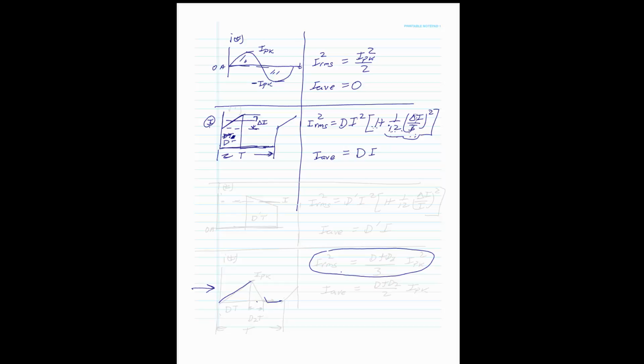The next one you'll see, of course, on the boost and the buck boost, is the diode current. And what are you going to see? Remember I said don't worry about that, I didn't include the ramp. Now I'm going to include the ramp. This is the ramp coming down, and this is during D prime T. And again, what is this?